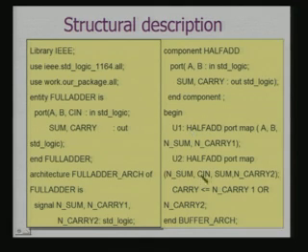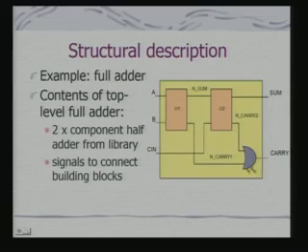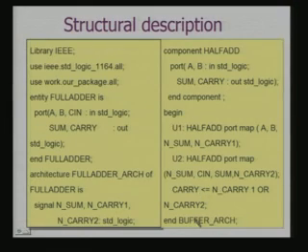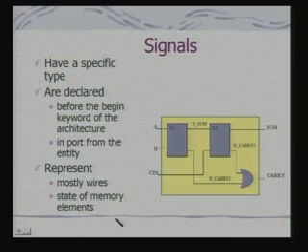Okay. So, here if you see, this half adder is doing a port mapping. So, what is it doing? A, B, and I have got sum, carry and this C in and carry 2. So, these are doing a port mapping, and why is this port mapping required? This port mapping is required because if you look into here, this is the connectivity that I want to represent. The C in goes to here, okay, and this output here should come at this point. Okay. So, this is what the structural description is all about.